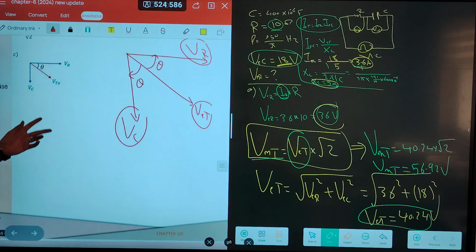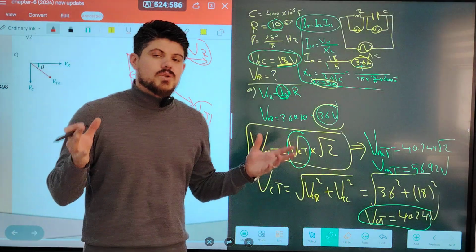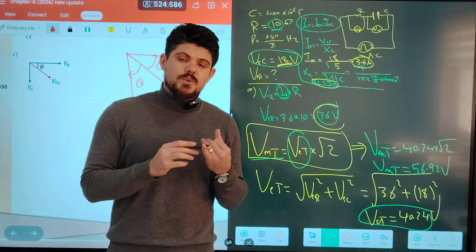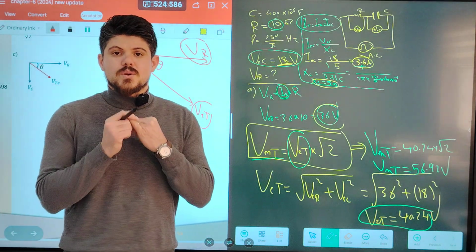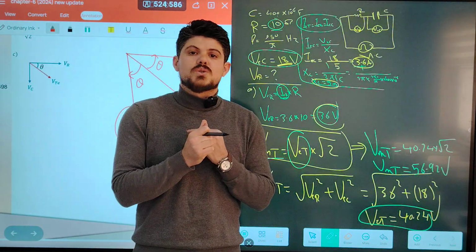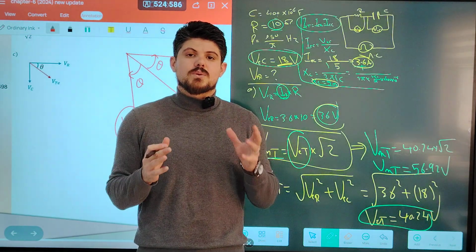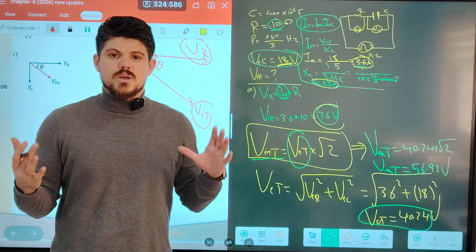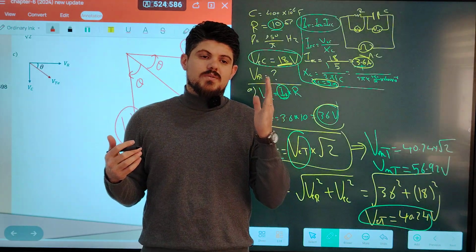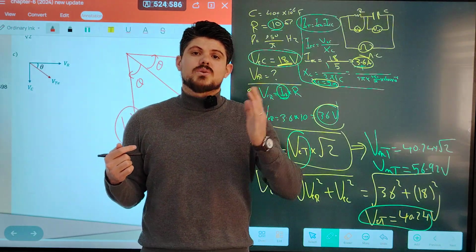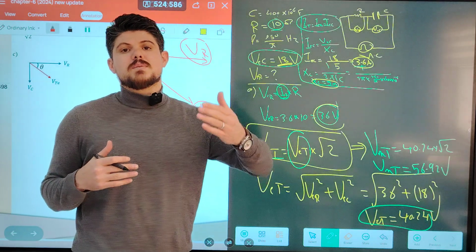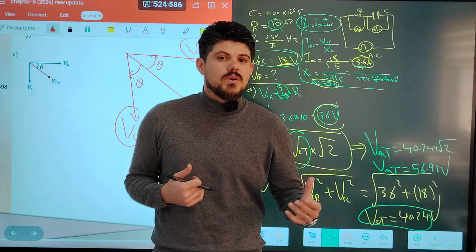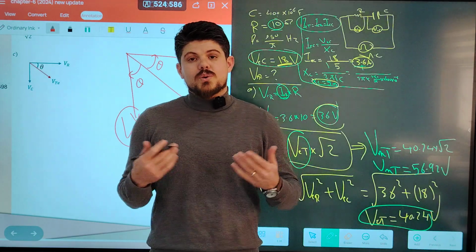Okay? Guys, we finished RLC series connection. Resistance, inductance, and capacitance in series connection to AC circuit. Just for reminding you, in pure resistance, there is no phase difference between the potential difference and the current. Both the reading of voltmeter and the ammeter increase and decrease together. When the value of potential difference reaches 0, the current also reaches 0. When the potential difference reaches maximum, current also reaches maximum in pure resistance. Okay, so the power dissipated follows Joule's law. The energy is generated, because we have power dissipation.